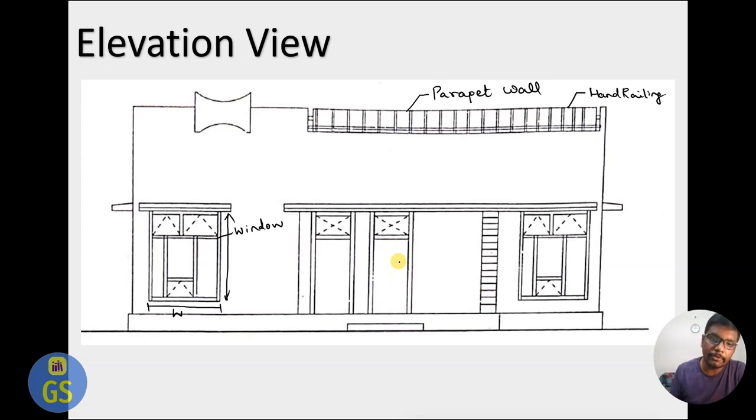Here you can see the door size, so there you can see the doors. What should be the door height, what should be the sill height, and with lintels, you can see the lintels here. This is a lintel, and this portion we call the sill height; basically, above the plinth we call this the sill height. These are the things you should know in order to start an elevation. We should collect these details in the field, or when you make the diagram we should show the heights we need to prepare in a drawing, and the same will be represented in the field during construction, right?